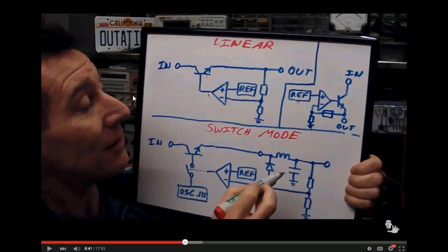But what determines how much we get through a transformer? I think we talked about that, induced voltage. We talked about what determines how much voltage we would induce into another conductor. So to induce a voltage into another winding, what do we need? We need a magnetic field, we need a conductor, and we need motion. What determines the amount? The strength of the field, the number of loops, and the speed of the motion.